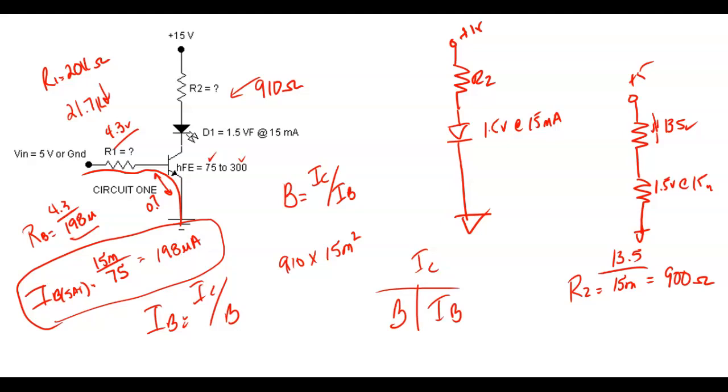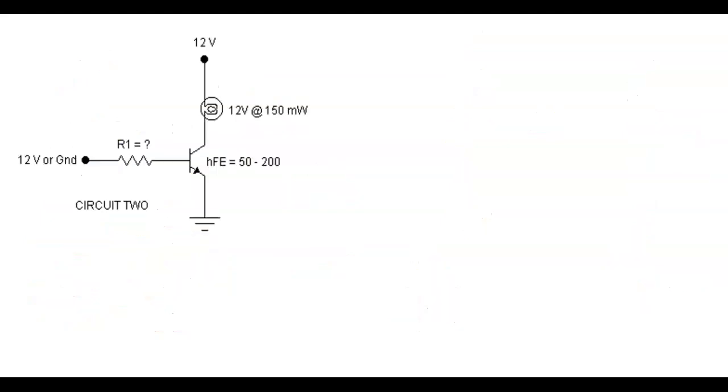And that's what you've got to understand, guys. I'm using 198 microamps to control 15 milliamps. So this guy is a current to control current. A very small base current controls the proportionally larger collector current. Okay, we okay? So the next one is basically the same.